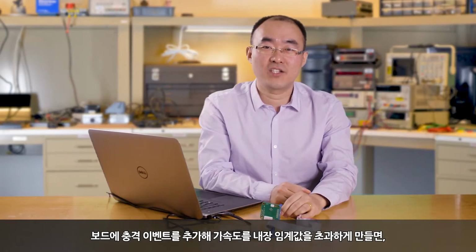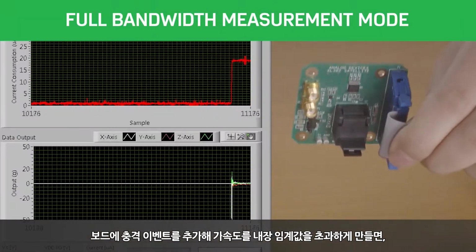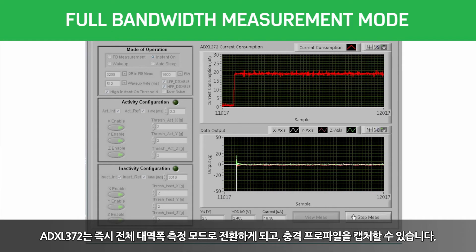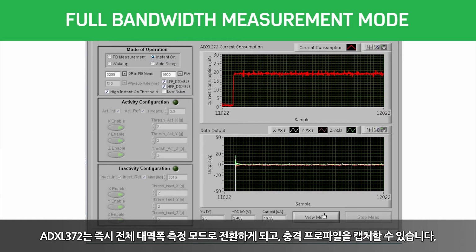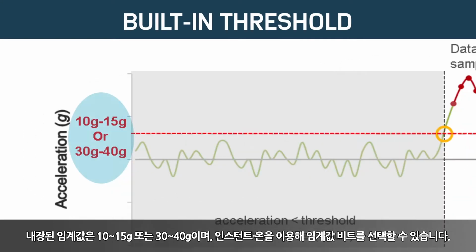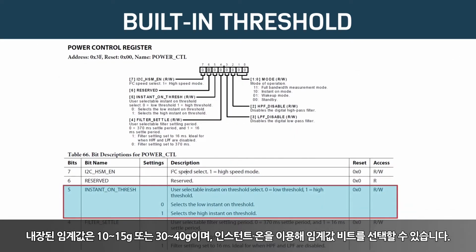When we add a shock event on the board to make the acceleration exceed the built-in threshold, like this, the ADXL372 switches into full bandwidth measurement mode immediately and can capture the impact profile. The built-in threshold is either 10G to 15G or 30G to 40G. It can be chosen by using the instant-on threshold bit.